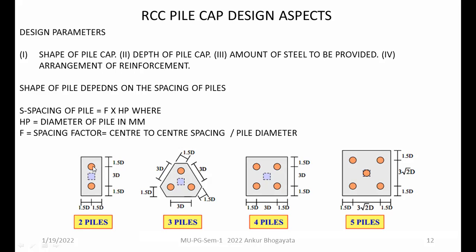And that will invite unnecessary upward bending moment because of the upward soil pressure also, because ultimately the pile cap is always in touch with the ground and experiencing some thrust from the ground. However, the downward force is usually so high that this upward thrust is usually neglected.